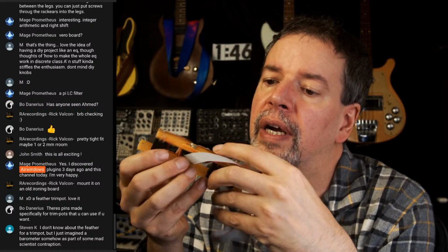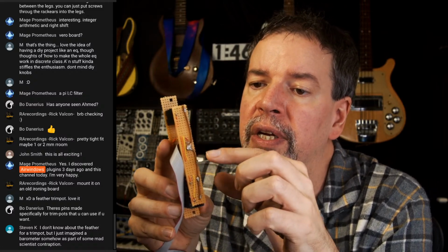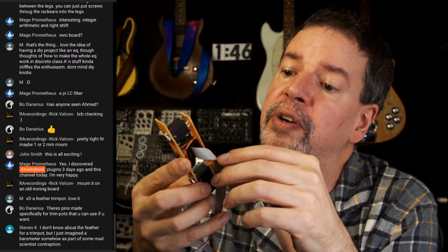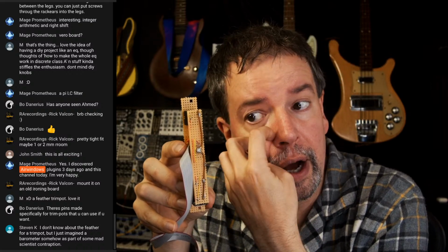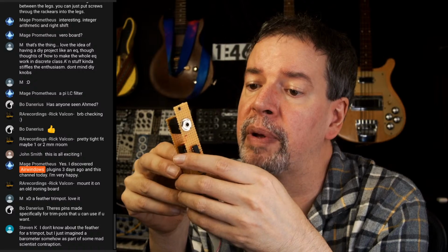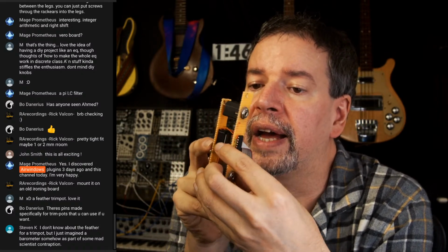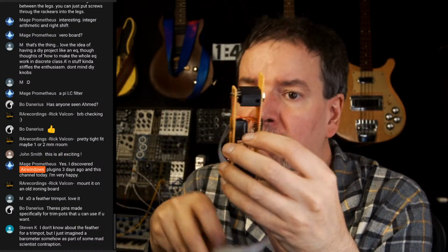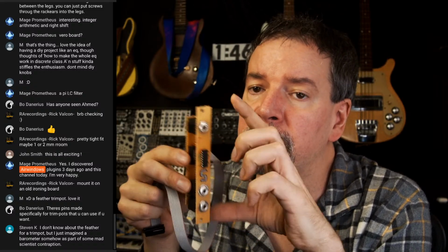I actually have a heavy bus wire on this, but this is heavier than you need. This is like house current wire, and 22 gauge would be quite satisfactory. Also these colored wires are not as heavy as the 22 gauge. So it's a work in progress, figuring these things out bit by bit. And as you can see, I have the jack here. That costs like 50 cents all by itself because this is a Eurorack module. But it's not using any other parts other than wire and the chips and the jacks.